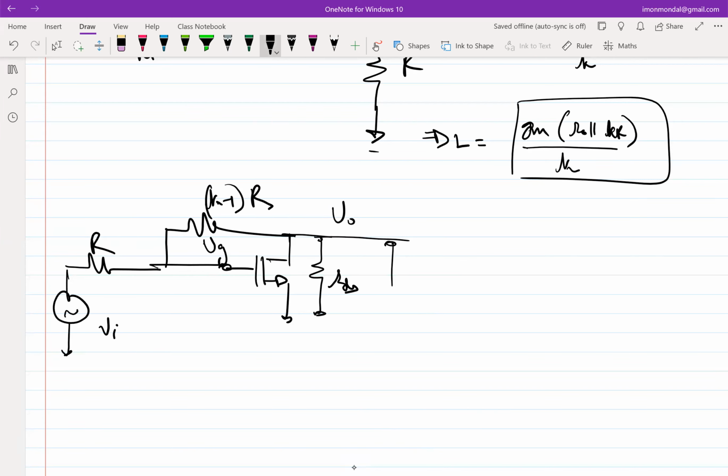And this obviously is a small signal circuit because we don't have any biasing. So if we have to bias, then we have to probably apply some VDD through RD. And we have to bias the gate also. We can simply do this. Okay. So in this case, let me ask you this. What is the problem if I just simply connect the input like this, if I am taking biasing into account?